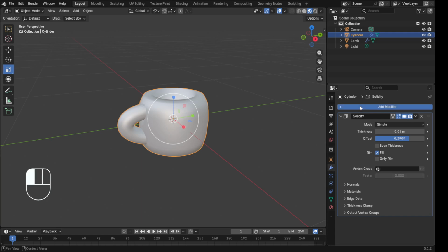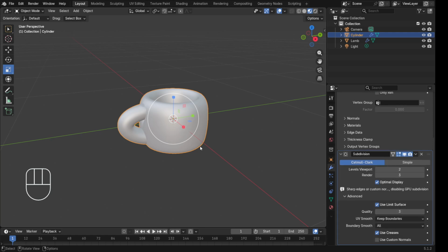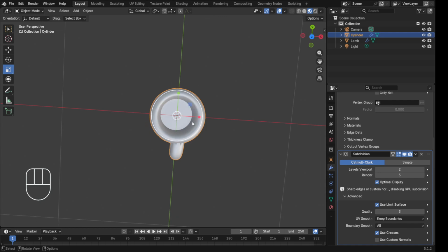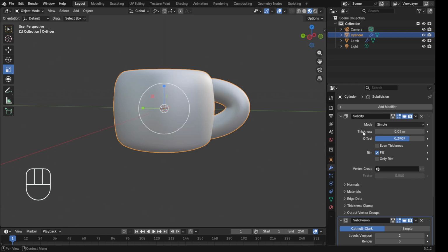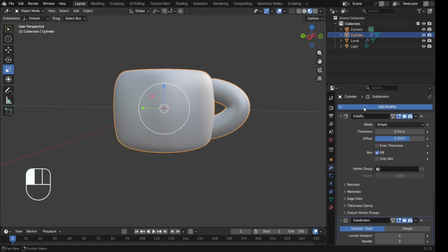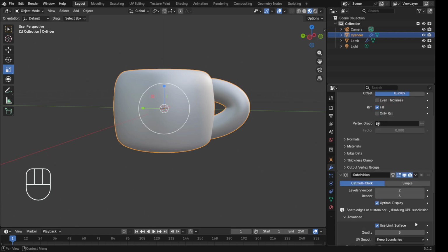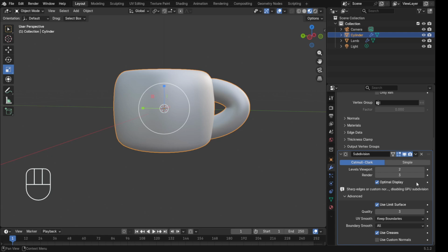You can also go to subdivision surface. Just be careful. Do not overdo it with that because you're gonna create some issues. You can see it at the bottom, but okay, that's not significant here. We can easily cover it, especially if you add the solidify there. You can also add a bevel modifier, that's optional again. You can just completely ignore it. The amount of bevel, because in this case we won't use it. But try bevel, experiment by yourselves.